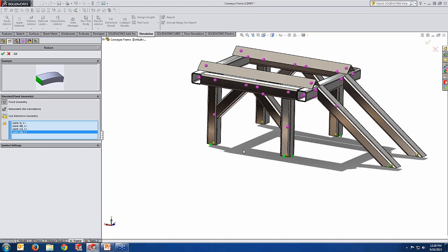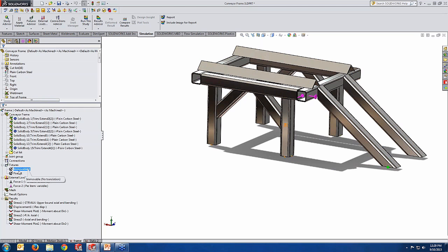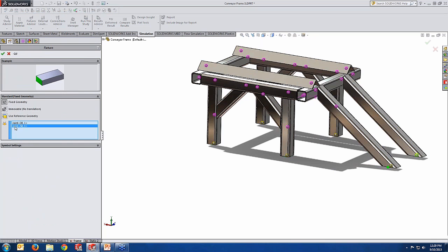Do not forget, you don't have any structural member or 3D one anymore. You have a 1D element, and it's going to be fixed at that node or at that point. By clicking OK, it is what we have created here. These joints and this joint are fixed.